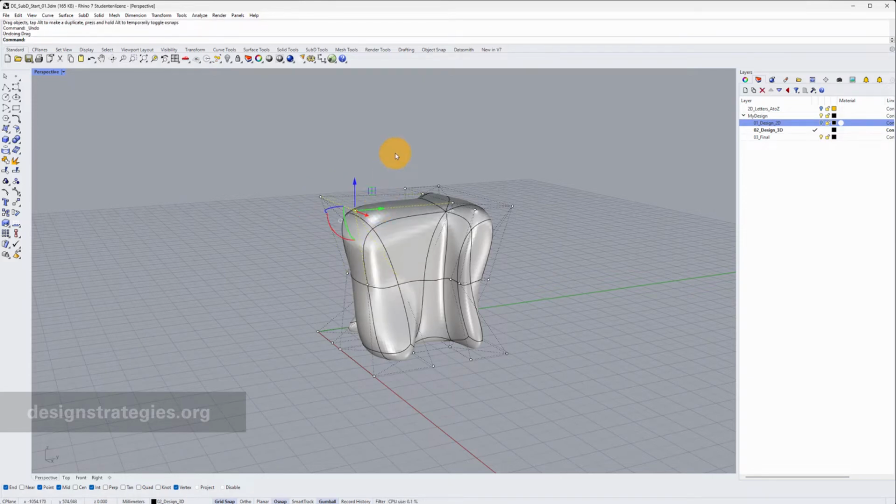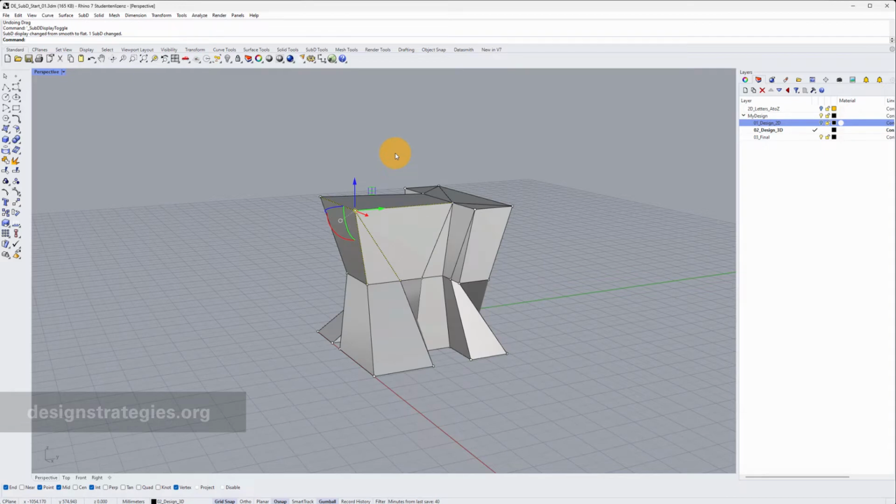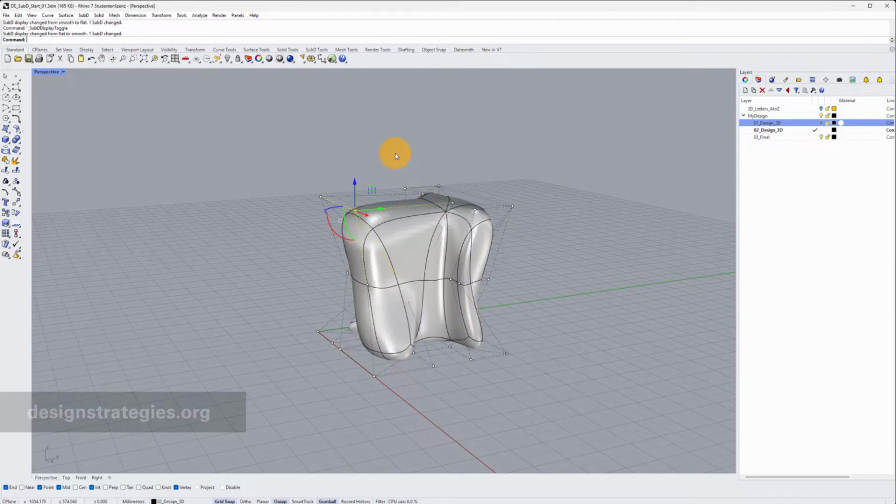What is really interesting is that you can also use the tab key. With the tab key, you can swap between this box view, which more or less shows the boundaries of the control points, and again the shaded object. So points on is really handy. You can also say, obviously, points off. Changing with your tab key between these two views is also really handy regarding modeling.